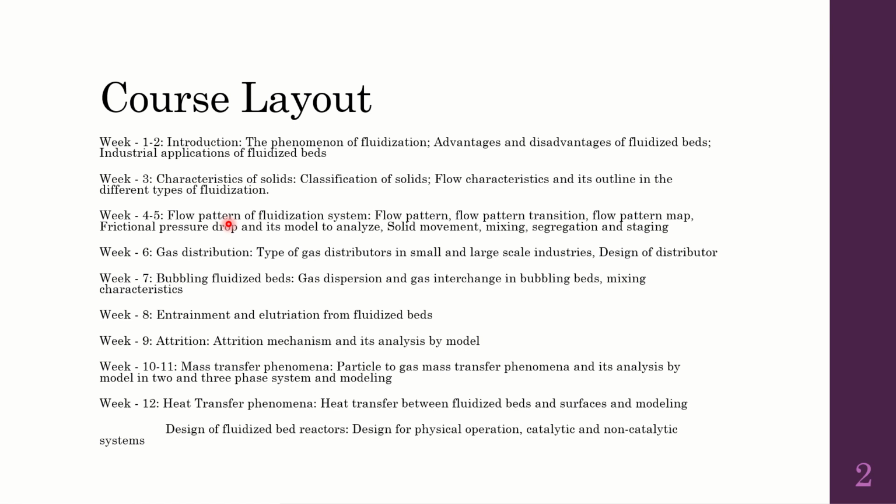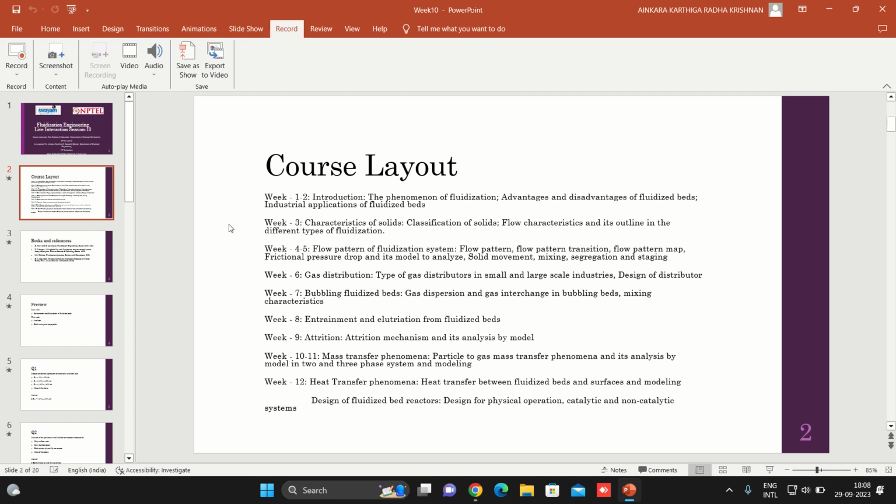I forgot the terminology for that slug, but it comes under slugging bed. Then once they start to break, the particle circulation also happens at that moment. Once the particles start to get thrown out, turbulent beds happen. After the turbulent bed, once we pass the turbulent fluidization, we have pneumatic fluidization, where carryover of solids does happen.